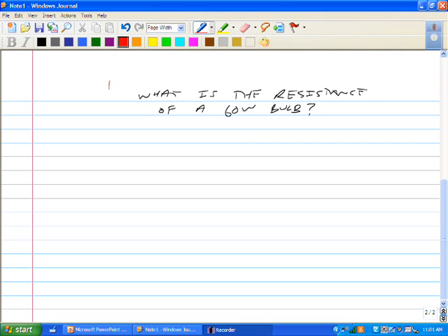Well, I know that the voltage is 120. Power is 60 watts, but I'm looking for R. We solve the current first and then solve for R. Okay, I could use P equals IV to solve for current first, and then use Ohm's law, V equals IR, to solve for resistance.